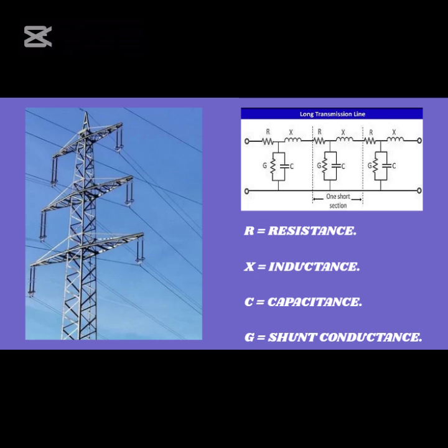5. Inductance occurs due to alternating magnetic field, while the capacitance effect is due to the electric field outside the conductor. 6. Phase shifts are caused by inductance, capacitance, and shunt conductance, but resistance has no impact on phase shift. 7. Shunt conductance occurs due to dielectric strength breakdown, or insulation breakdown of the surroundings. 8. In DC transmission lines, the effects of inductance, capacitance, and shunt conductance are relatively insignificant compared to AC transmission lines.